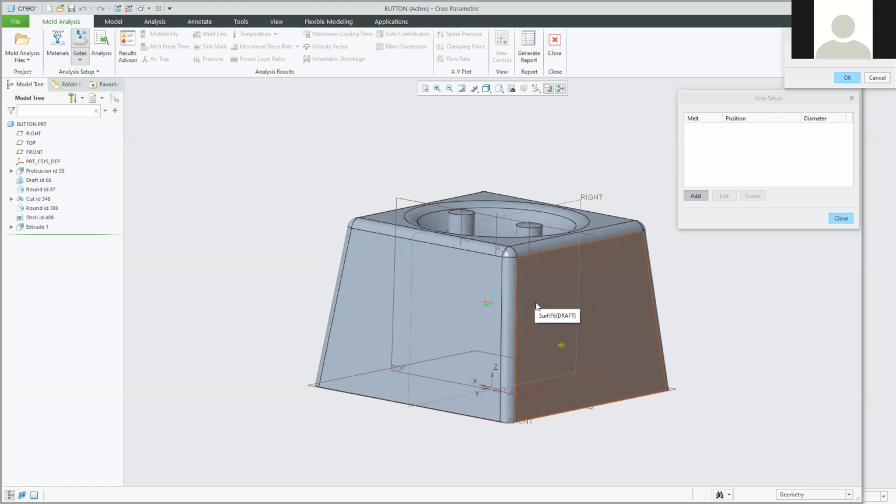So what you might do in this case is momentarily quit out of molding analysis and think to yourself, right, I want to put a gate and I want it dead center in this face. I want it in the center vertically of the face, and also in the center horizontally, for example. So I'd create a sketch on the face first, and I'd probably create a vertical line and a horizontal line, and then I'd use constraints to lock that horizontal to the center point of that vertical edge, and to lock the vertical line to the center point of there.